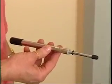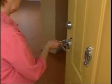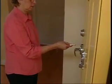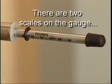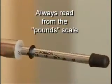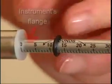Most commercial gauges look like this one. It is designed to measure the pressure it takes to open a door with a closer. Remember, if there is no closer, you can keep the gauge in your bag. There are a couple of things you need to know about the pressure gauge. There are 2 scales on the gauge, pounds and kilograms. Always read from the pound scale. Set the top black O-ring located on the plunger rod to 0 down against the instrument's flange.